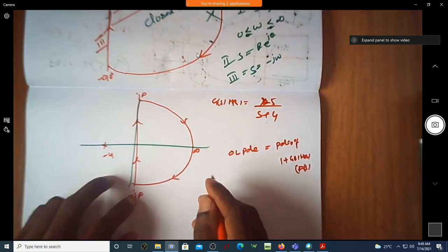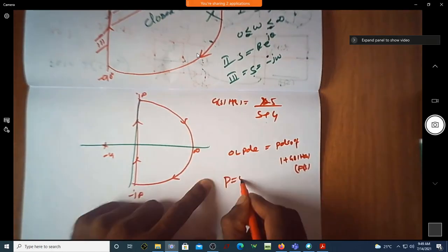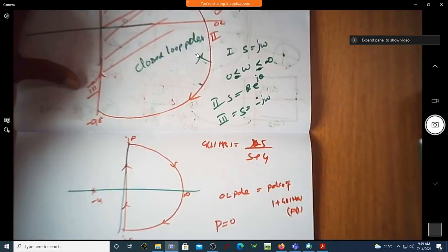So now, is this pole enclosed by this contour? No, sir. So shall I write P is equal to 0? What was P here? How did we define P? It is the number of poles of F(s) enclosed by the contour, a random contour. Correct? Yes. What is this P now for this specific contour?